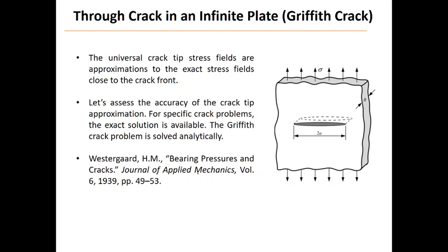Now we have a simple problem. I hope by now you get an idea of kind of engineering. If we have a solution, let's find a simple problem and see if we can predict that simple problem correctly first. The simple problem is going to be the Griffith problem, because this is a problem where the exact solution is available. Inglis derived one solution for it. It works across the whole plate, not only at the crack tip, and there's no approximation to it.